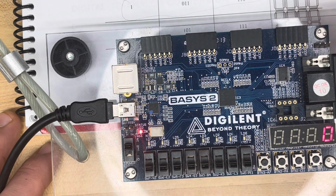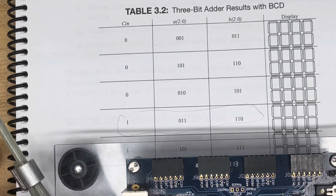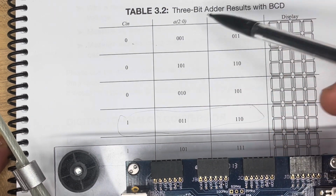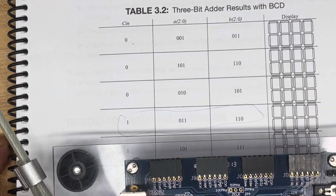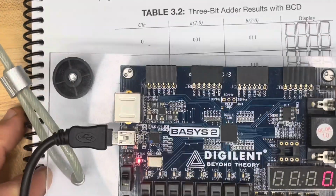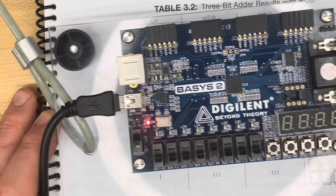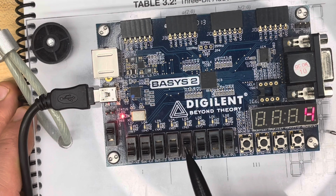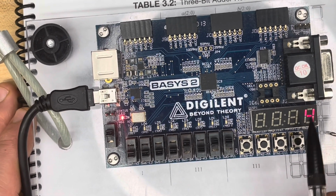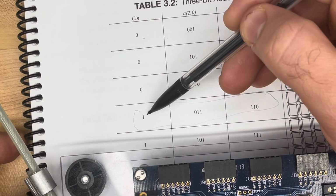So if we want to represent a case, let's start with a simple one. Let's say the Cn is 0, so we are adding 1 plus 3. How much should we get? We should get 4. So the Cn is 0, so we don't need to worry about this. Then we have 0, 0, 1, which is 1, and then 0, 1, 1. That's going to give us 4, because 3 plus 1 gives us 4. And remember that we didn't press the push button because it is 0.